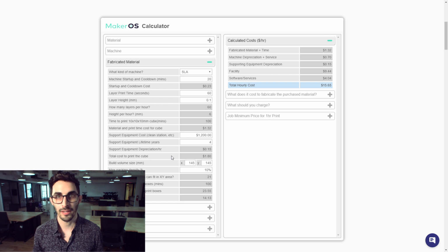And depending on the style of machine, it can be higher or lower. Look at the manufacturer's recommendation for that kind of calculation, but you can kind of be smart and look at your own parts and do a rough estimation. If you want to do an exact estimation, you really can look at the cross section of the layers and calculate the actual amount of surface area per layer that those parts are taking up.